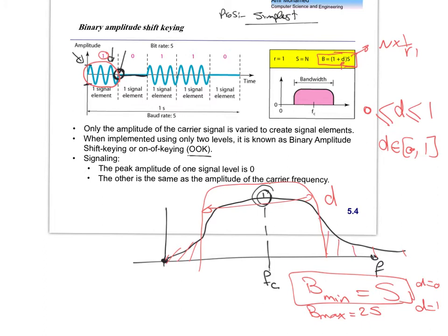Of course, yes. It's not about the filter, because the filter is at the sender side. We can make the filter as wide as we want, because at the transceiver at the sender side, there's no problem. The problem is, what is the bandwidth? What is the physical limitation of your transmission medium? Your transmission medium has certain limitations in terms of the maximum frequency components that it supports. So we are restricted by this.